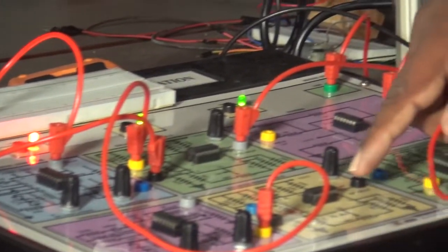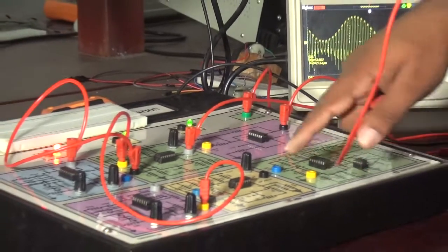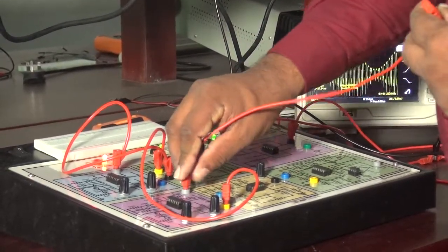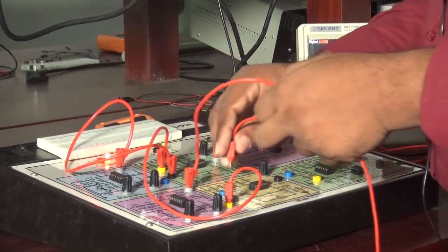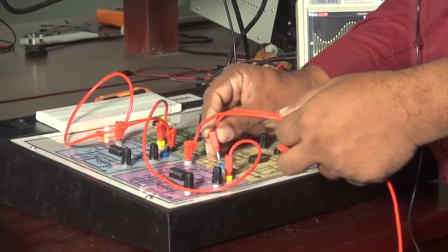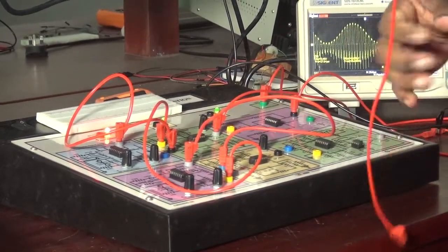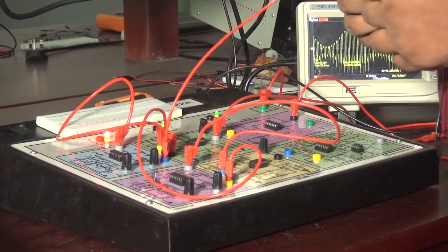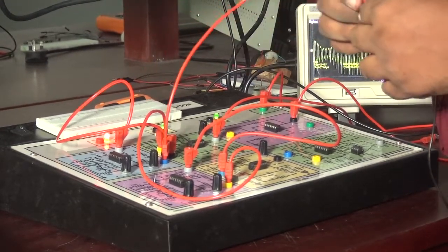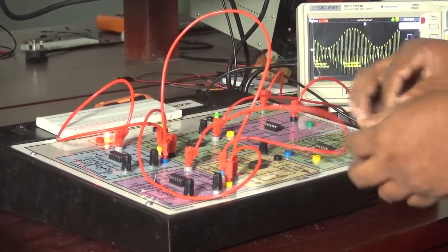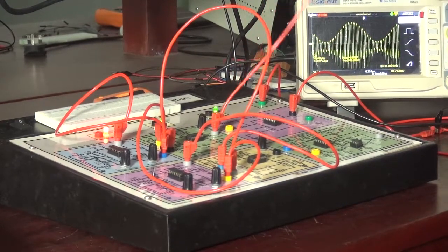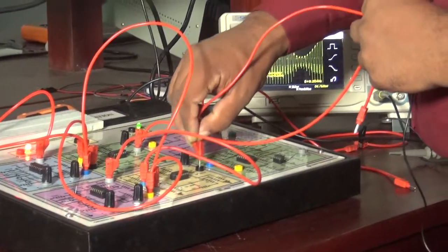So, I am going to connect the message signal and carrier signal to the other modulator also. Here we have a 0 phase shifted carrier signal, and I have connected it to one modulator. And I have my message signal, that is also 90 degree shifted, and I have connected it to my other modulator. So, this is one amplitude modulator and this is another amplitude modulator.